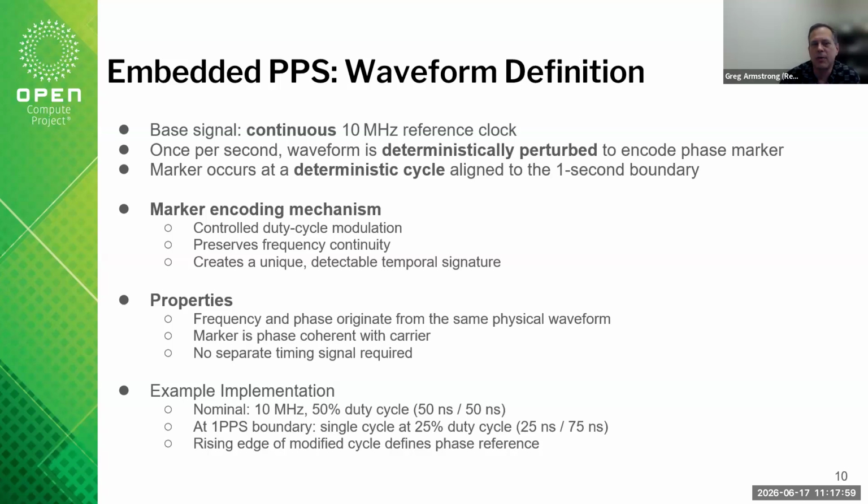Most of the time when you're distributing a clock such as 10 megahertz, it's a reference clock. It's not itself used to actually distribute physical data. It's not used directly at a SerDes interface or directly to send something over the wireless infrastructure, right? It's more of a reference clock that will get multiplied up to a higher frequency somewhere else. And so having a distorted duty cycle doesn't really impact it as a frequency clock.